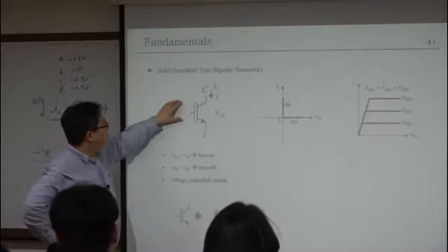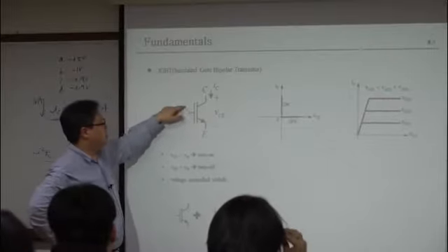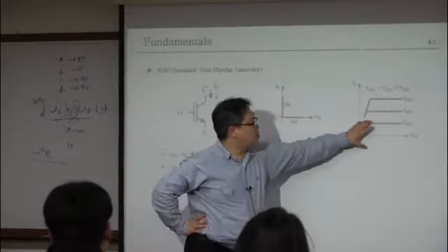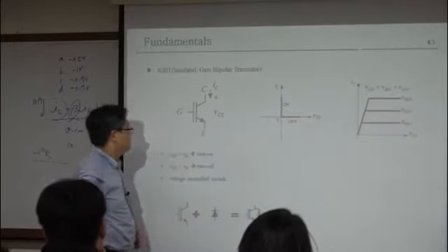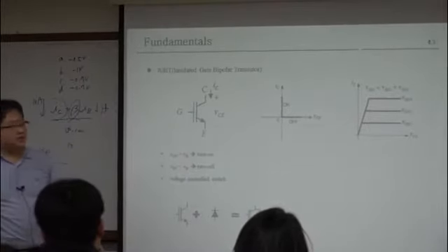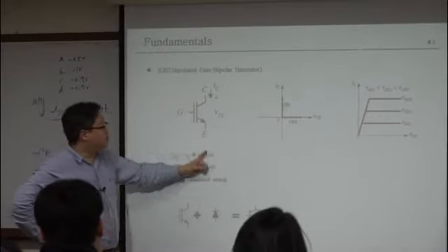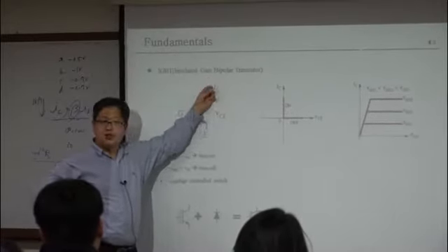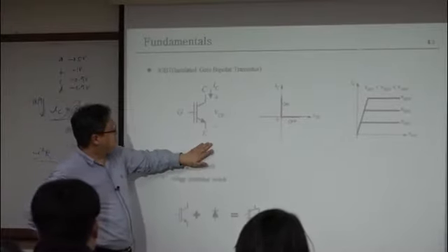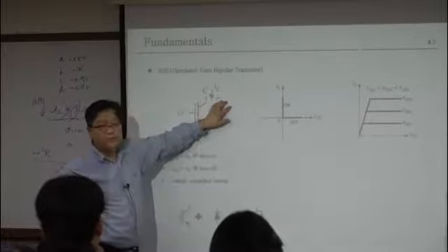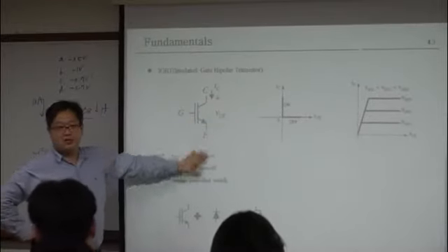But now, in IGBT, that is the gate. That is the VI characteristics of IGBT here. Unlike the MOSFET, IGBT doesn't have the capability of reverse current flowing. So to flow the current in reverse direction, I told you, you should have the anti-parallel diode like that.